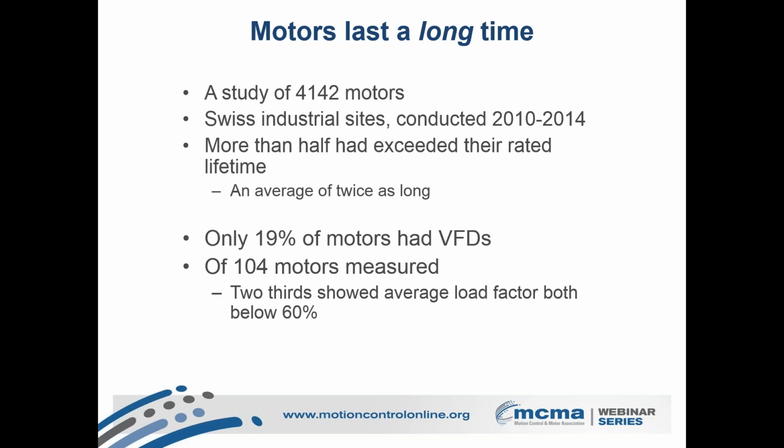They get out there, they get rolling, and they just keep ticking. 19% of the motors had VFDs, the rest were still running continuous speed. And one of the really useful things going on right now in terms of energy savings is putting VFDs on things like fans and pumps, so that instead of having the motor running flat out all the time